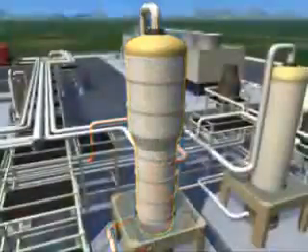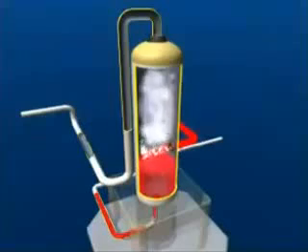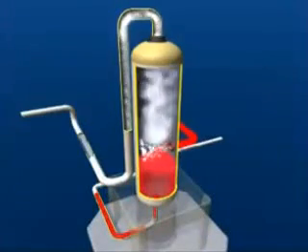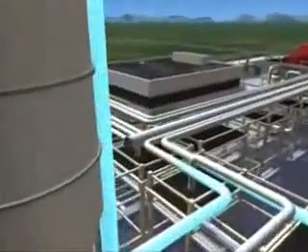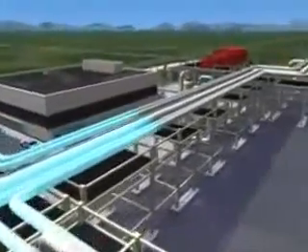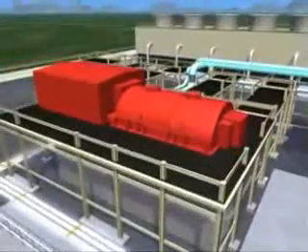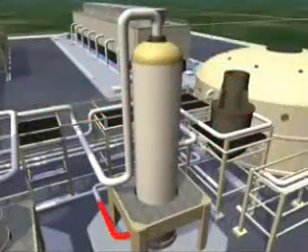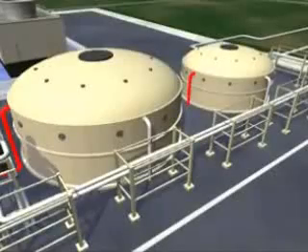The flash process continues in the low-pressure crystallizer. The remaining fluid is again flashed, this time at a lower pressure to produce low-pressure steam. All of the low-pressure, standard pressure, and high-pressure steam is delivered to a turbine. The fluid that is not flashed into steam flows into the reactor clarifier system and is then returned to the geothermal reservoir through injection wells.